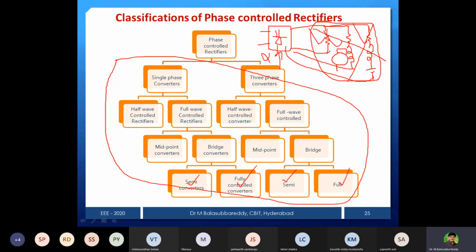So for our motor, you need to check the performance, the speed of the motor. Here, controlling the speed, whether it is armature control or flux control, or in the same setup I may need both, that is above the rated speed or below the rated speed. So all these performances we can analyze. Preferably this concept will come into the drives subject.